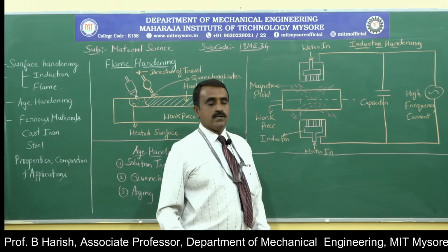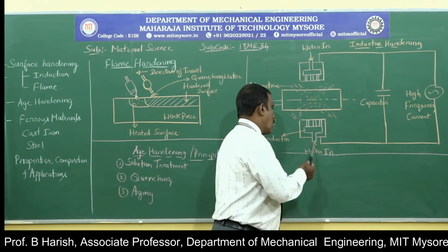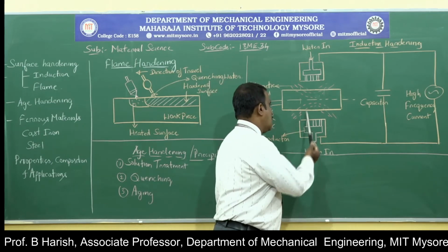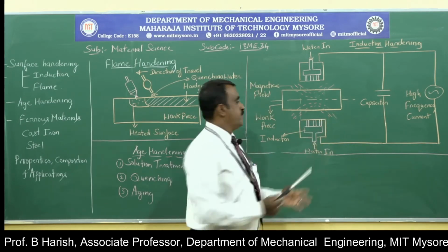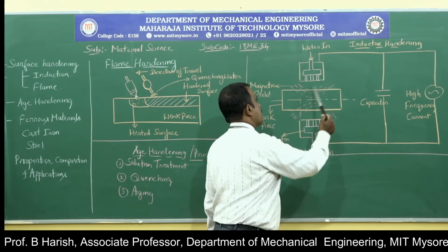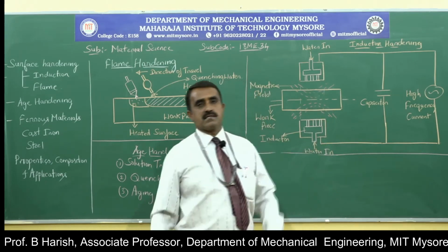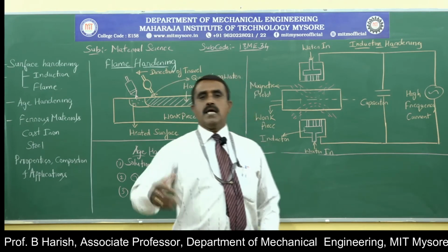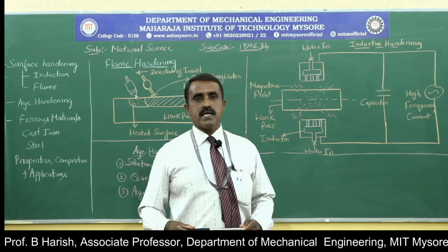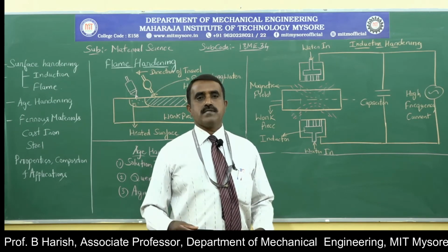Immediately, water will be continuously circulated. Water enters through this and gets sprayed over the heated surface in this direction, similarly in this direction. So immediate cooling is done. Immediate cooling or immediate quenching is done. Once immediate quenching is done, the surface gets hardened.